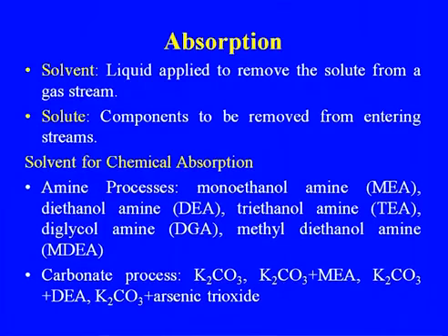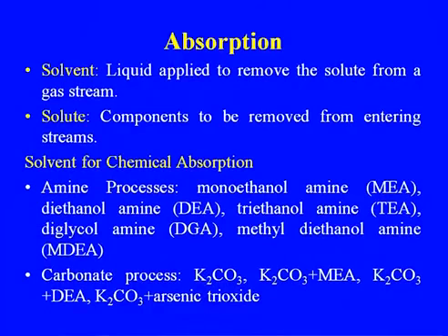There are two parts in this: one is the solvent and another is the solute, which is to be removed from the gas stream. So a liquid is applied to remove the solute from a gas stream, the components to be removed from the entering stream. Various solvents have been developed, because there has been continuous development in solvents also. Now the amines: MEA, DEA, diethanolamine, or triethanolamine, diethylene glycolamine, or methyl diethanolamine.